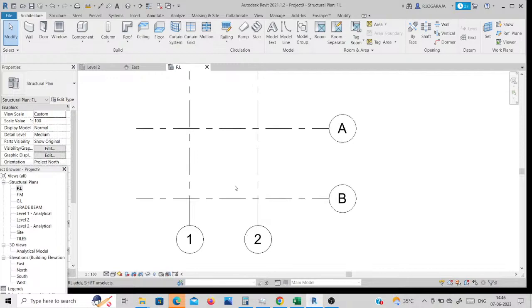The third step: you create the grid with only the center line marking. Then you mention this. One direction is 1, 2, and another is in alphabetical order. The opposite adjacent directions are A, B, C, D in one and 1, 2, 3 in the other.